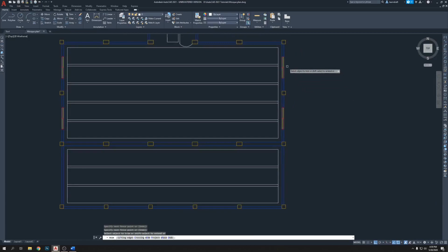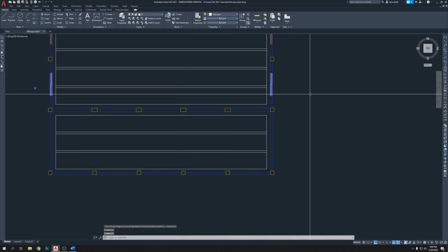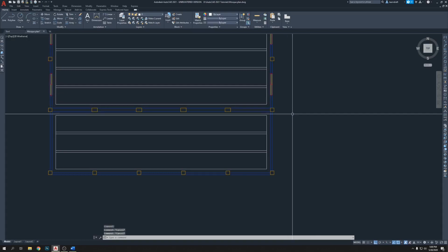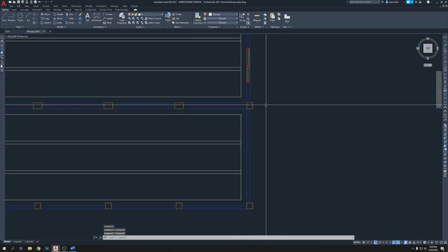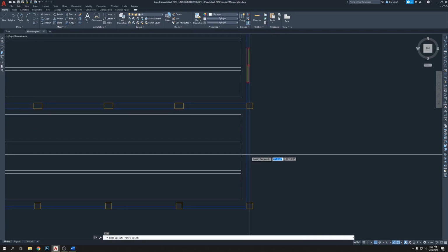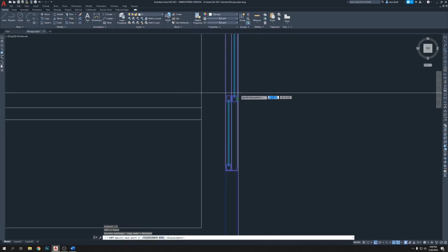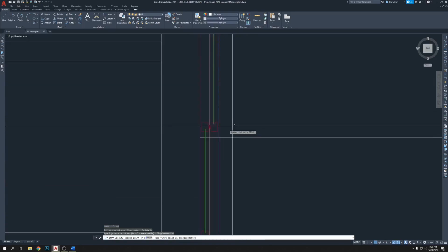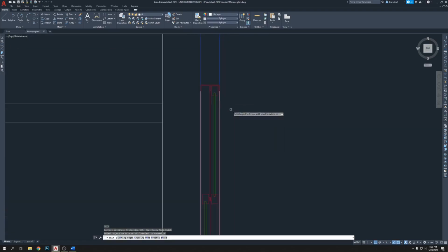Now we're gonna bring some windows here. Okay, let's take these 2, but it's going to set on the center. Now we need to make a center point first, then bring it. How are we gonna bring it? We're gonna select from the center of this one. Yeah, makes sense. Alright, so L, enter. Let's say this is the center line. Select this one, copy. Where is the center? Here is the center. Bring it here, click here. Select this one, delete. Trim, enter.